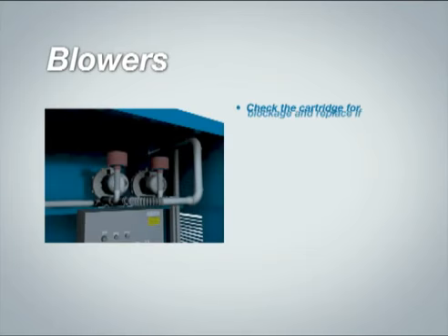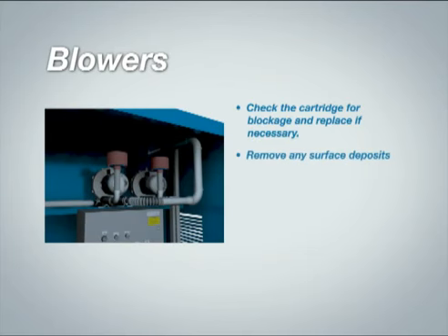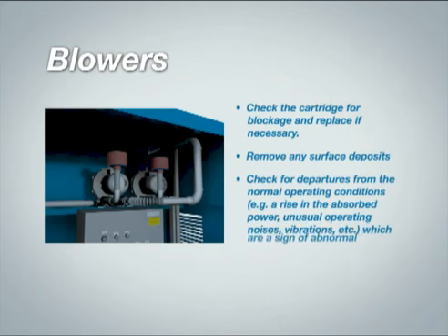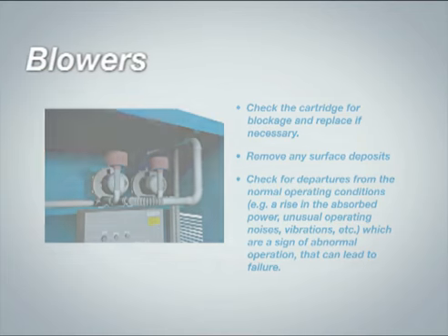Blowers. Check the cartridge for blockage and replace if necessary. Remove any surface deposits. Check for departures from the normal operating conditions, that is, a rise in the absorbed power, unusual operating noises, vibrations, etc., which are a sign of abnormal operation that can lead to failure.